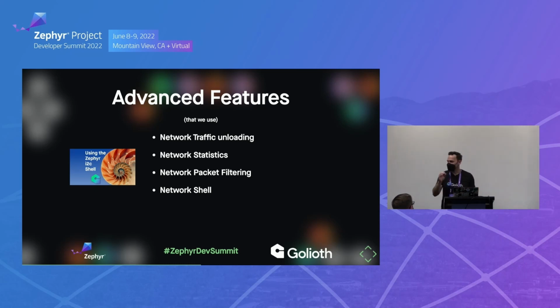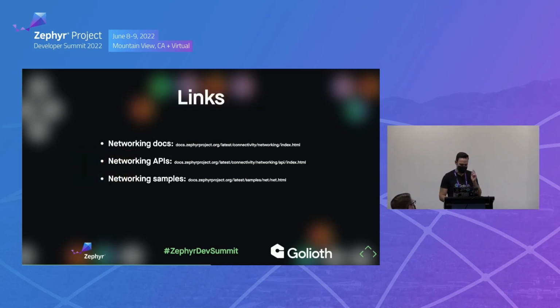And even things like a shell. I don't know if we showed in the last talk, but Zephyr has all these powerful shells that you can just connect your UART to, start running commands, and without even writing any code, test what's going on. So, show me the packet, what's the IP address, things you would expect from a full-blown operating system running on your tiny microcontroller. And again, all built into the networking stack. Anyway, there's a ton of documentation on networking. 99% of applications don't even have to read any of that. All you need is the few samples related to HTTP, UDP, WebSockets, whatever you want, and you're good to go.